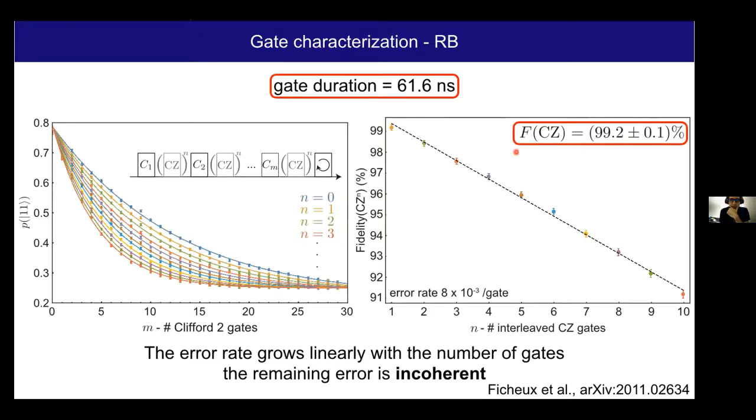So it's slightly longer because in practice, the gate has finite edges, but it's not tied to the qubit frequency. So we can just get a very fast gate. This is actually one of the fastest microwave activated gates on superconducting circuits right now.